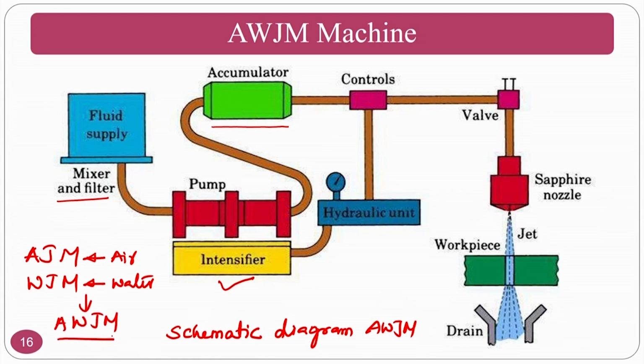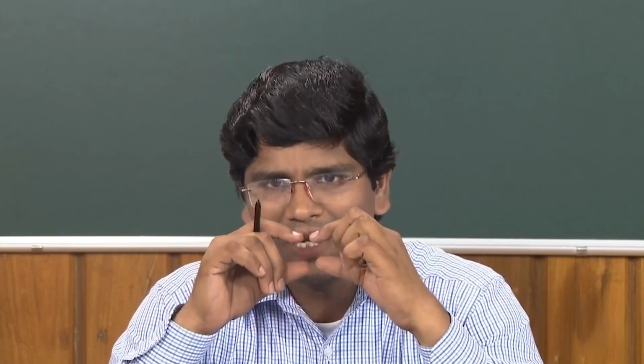The advantage of abrasive jet machining is that you have the abrasives, you can cut, but the only problem with abrasive jet machining is that the divergence will be there, so stray cutting will be there. In order to counter it, what will happen? On the other side, in water jet machining, the capability of water to cut is very less. However, the coherent nature of water is there.